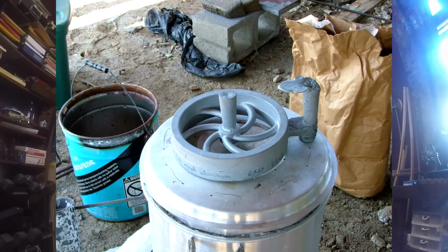Now the casting looks pretty good. I don't see anything that's facing us that looks bad, but look how they fed it. They poured the metal, and this is aluminum, down something you could practically put 2 or 3 fingers in, and even though they did have kind of a splash basin underneath to absorb some of the turbulence from that pour, that metal was poured directly into the mold cavity.